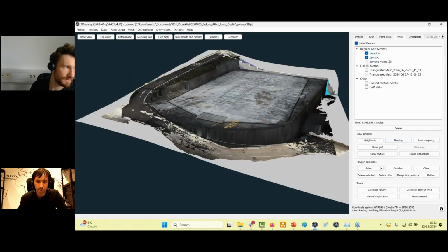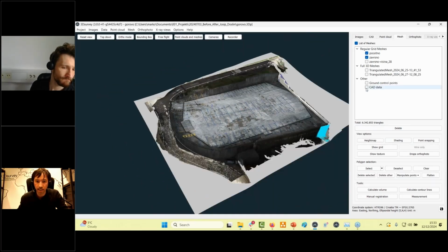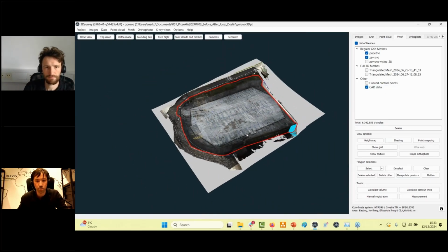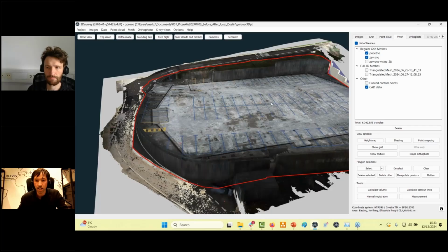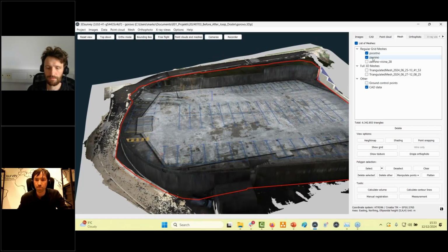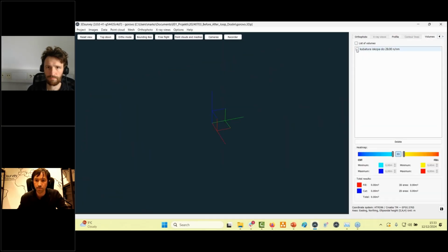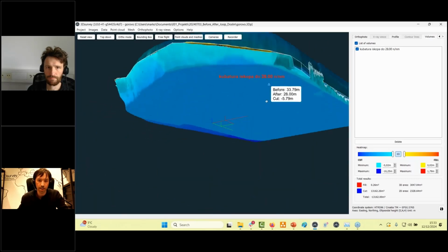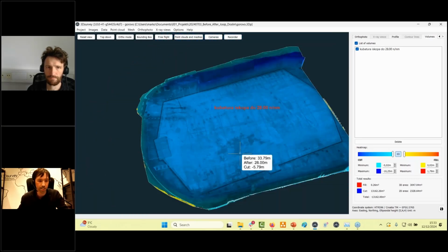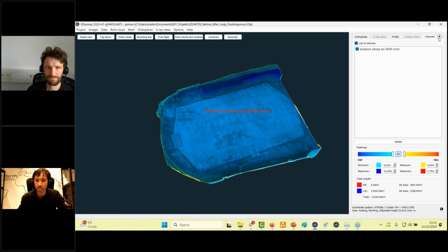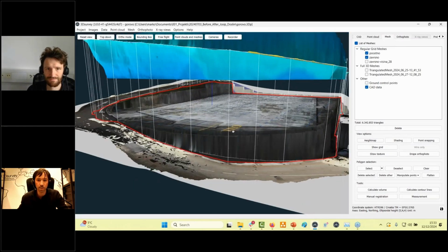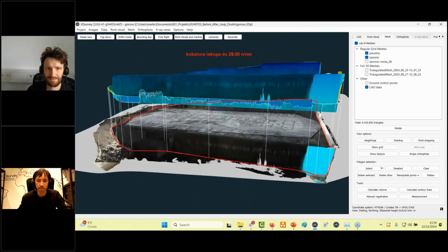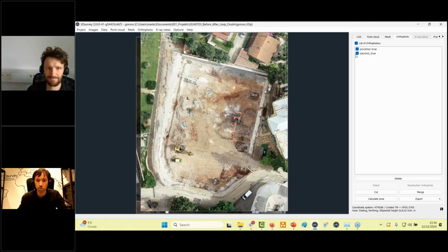And actually, they also imported a CAD boundary, so you can select your area of interest for volume calculation also based on CAD data. You can draw it in 3Dsurvey or you just import it. And right now I have my first plane, second plane, and based on this, you can calculate out the volume. And here we can see the volume actually from the 2 surfaces calculated in 3Dsurvey. So pretty nicely visualized everything and super accurate at the end. So I would just like to say there's no other technology that can do this job so nicely as this, okay? And beside, of course, you get also an orthophoto.